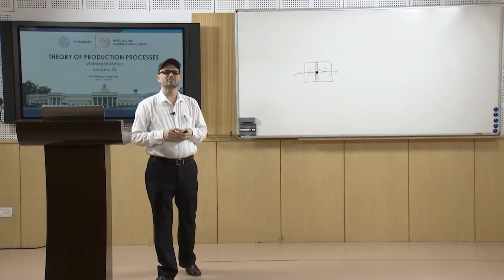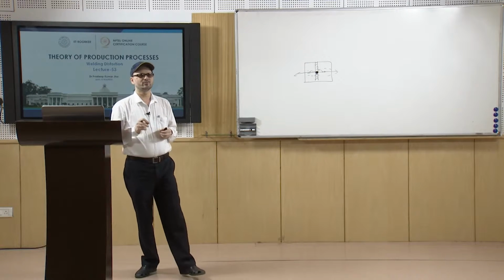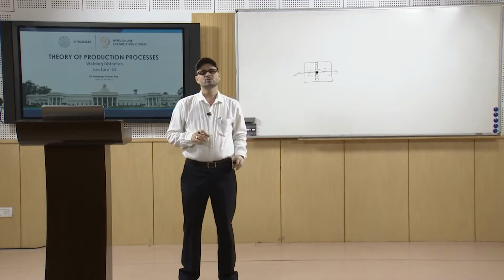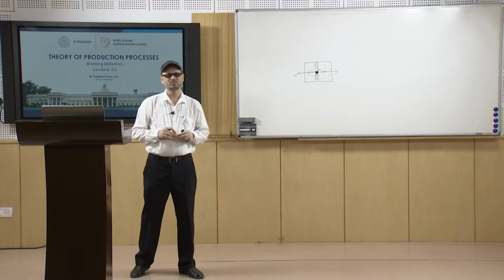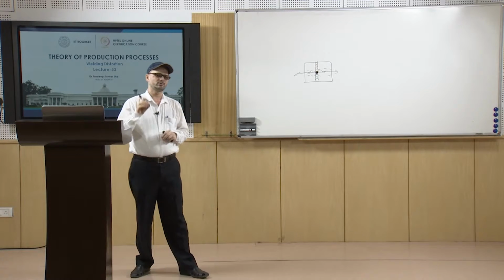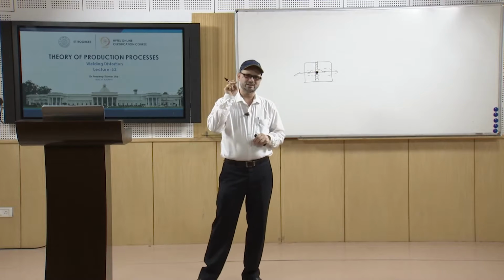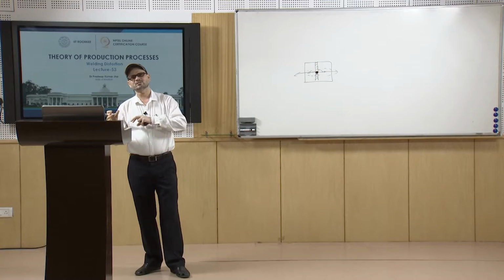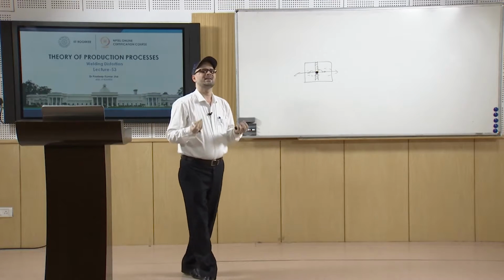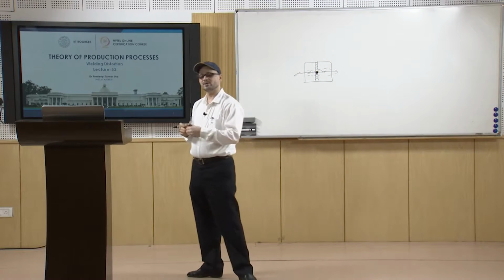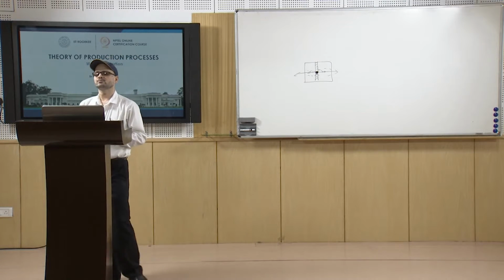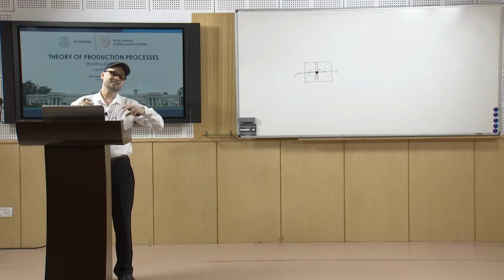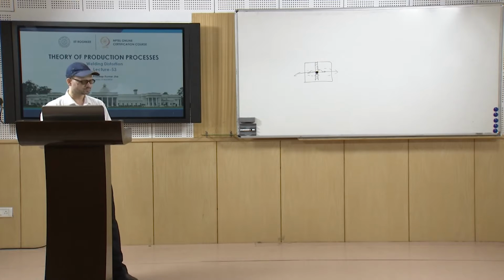Like if you take the example of electron beam welding or TIG welding, as compared to flame welding. In the case of flame welding, oxy flame welding or so, you will have a large amount of spread. If you take electron beam welding, which is just like a beam, it goes and does the welding operation. So, in the case of electron beam welding, you will have a lesser amount of distortion as compared to flame welding. That is why the concentrated heat source is preferred over the spread type of heat source.